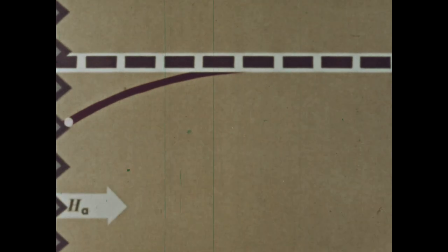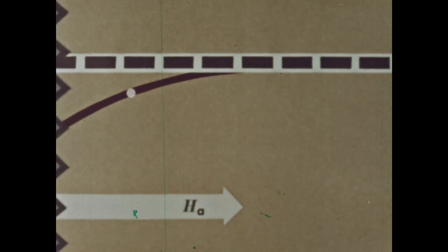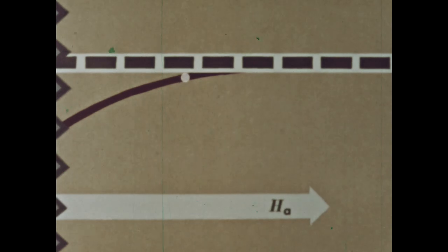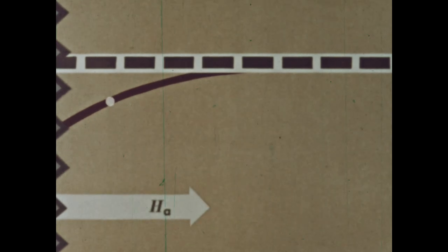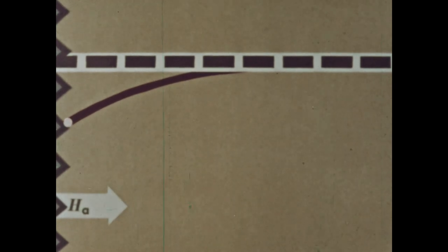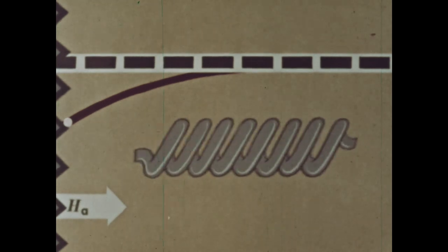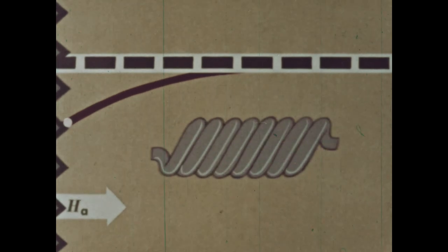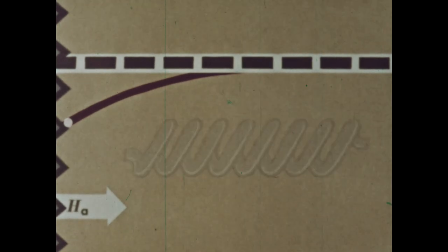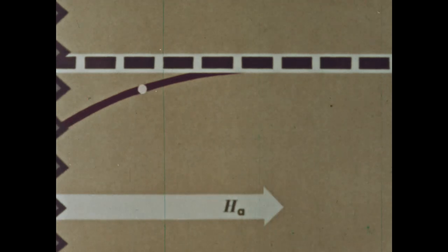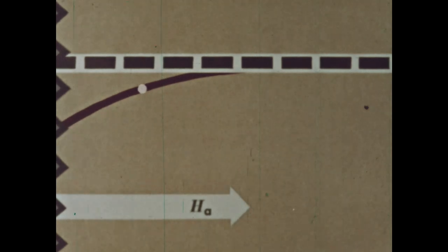Notice that here, H and B increase and decrease along nearly the same line. The domain rotation process gives rise to little hysteresis. The energy supplied by the field in overcoming the crystal's anisotropy is mostly returned when the field is decreased, just as the energy stored in compressing a spring is returned when the compression is released. This means that the domain rotation process is largely reversible.